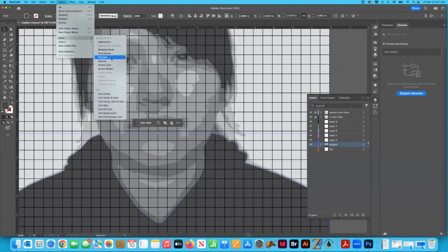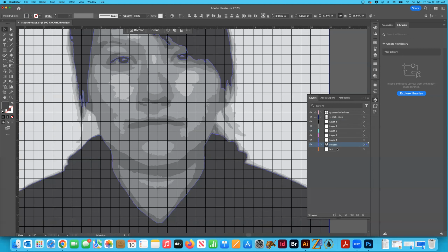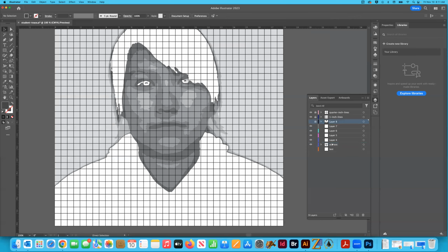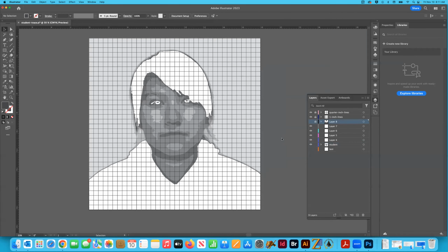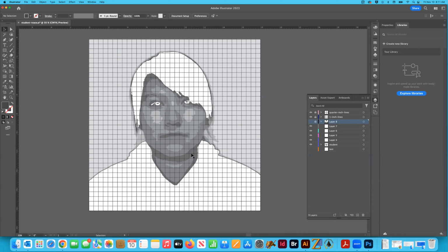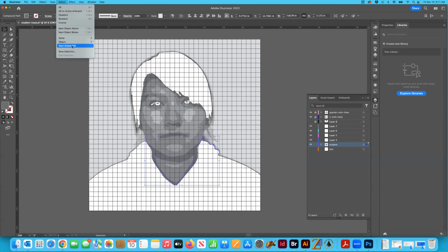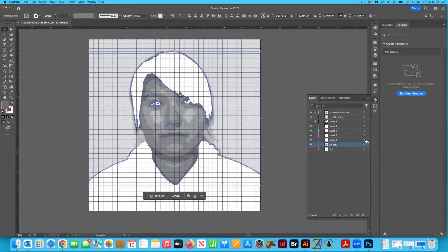Select, same, fill. And by the way, I don't think I really talked about this very. Notice how there's a blue outline on all of the vectors that I just selected. Well, look over here. There's a little icon. It indicates selected art, and you can drag that to a different layer, lock it, make it go away. Okay, so this is essentially layer management, which is really, really important for a designer to be hyper focused on, if you ask me. Select, same, fill, boom.